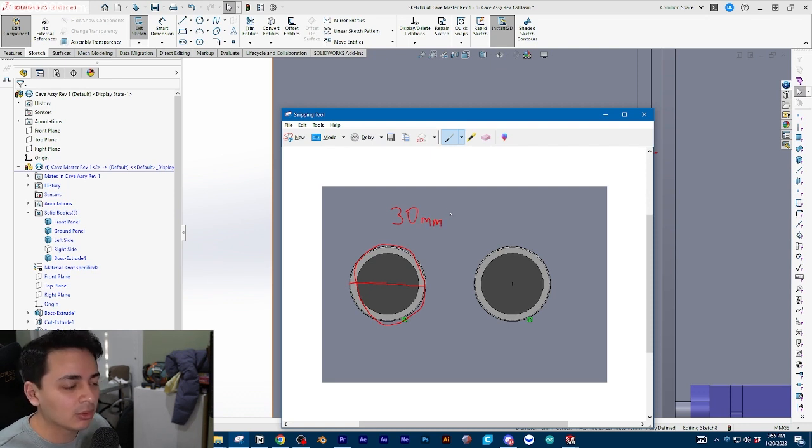We want our hole to be slightly larger. So you're going to offset by 0.25 millimeters on each side. So this here is going to be a 0.25 millimeter offset, but all the way around the circle, whoops, let me do a new circle in blue. All the way around the circle, you're going to have 0.25 millimeters on both sides.